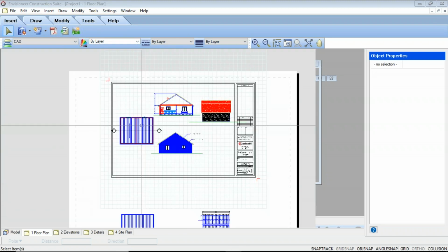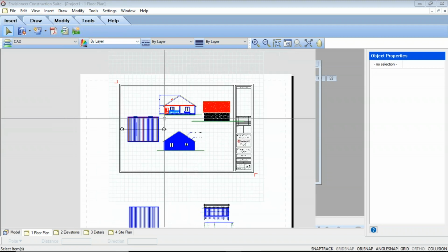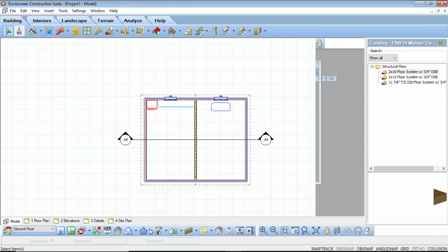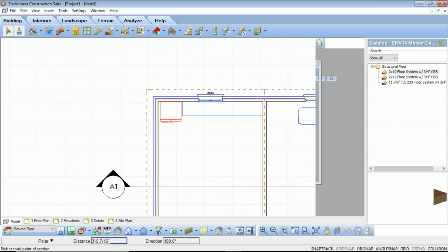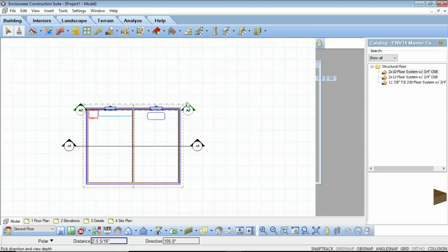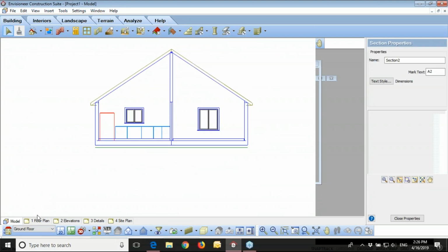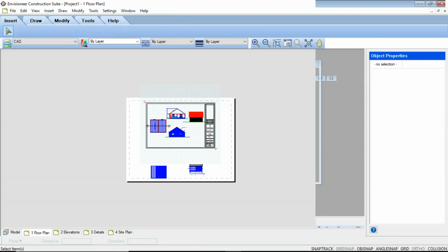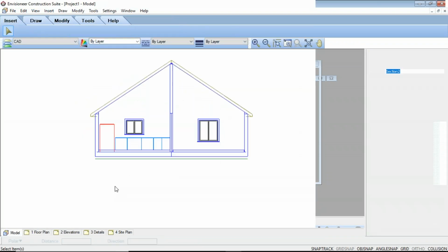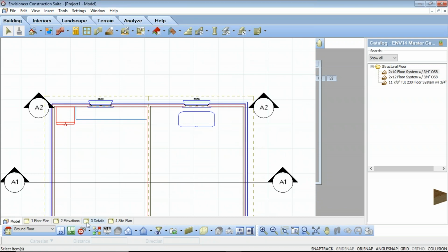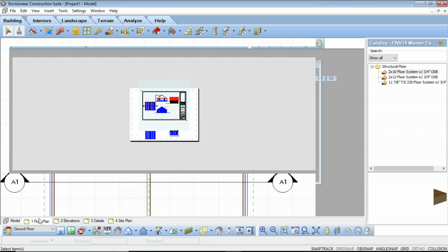If you only wanted to see just the framing of a wall in an elevation view, you could also try and do it this way. If I create a new section, you could do something like this. And from there, what you'll be able to do is on your sheet view. So basically, I'm just taking a section of just this portion of the wall. So I'm not going to see any of this extra framing back here. I'm only going to see the framing from here and from here up.